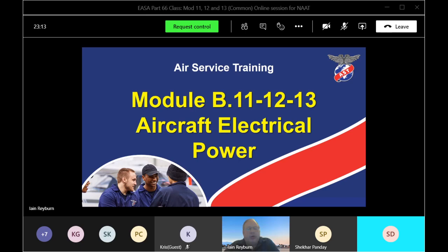So that's what I must have here, 115 volts AC. And here's my voltage regulator. It's sampling the voltage just before it goes into the generator contact breaker. Why there? Okay, why there?